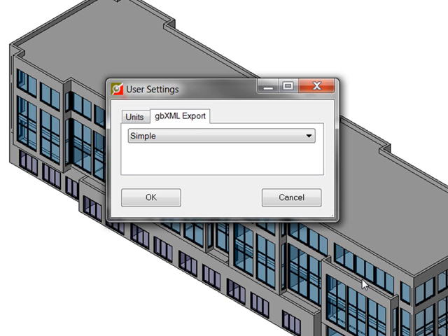So if we actually think about energy analysis or any type of building analysis, we're looking at what's happening with the daylight spilling into the spaces or solar radiation and how that's being blocked or changed by, just to keep on this example, those particular mullions. So having something very detailed, let's say it's a 1 centimeter or 1 inch mullion, is that really going to matter in the scheme of your project? And often you'll find that because it's early stage, you're just looking for early numbers. You don't need that. So please try to keep it as simple as possible. That's really one of the first steps that we have.